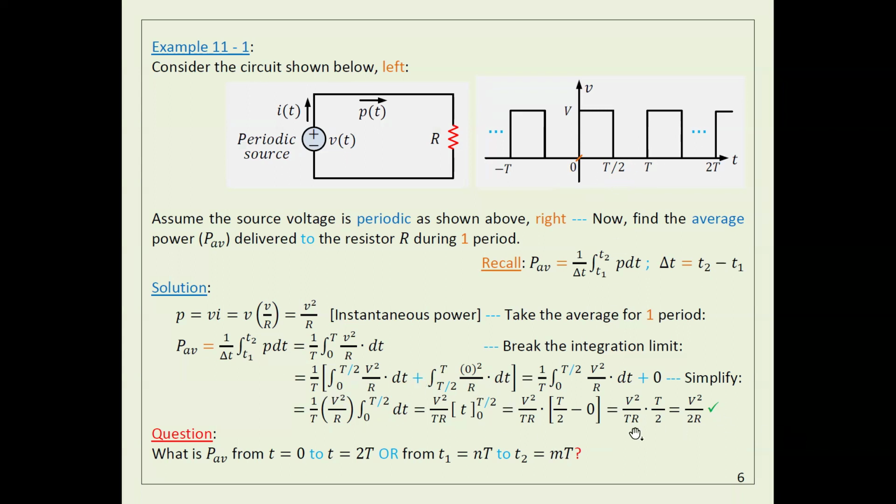And then if you follow the calculation, you find the power should be V squared divided by 2R. Half, because half of the time. It's not V, capital V here is the DC value, whatever you have here. Because half of the time I have power, the other half I don't. So the power will look something like that, V squared divided by R, but the value will be different. Here we have some power and then 0. That's why I'm interested in the average value.